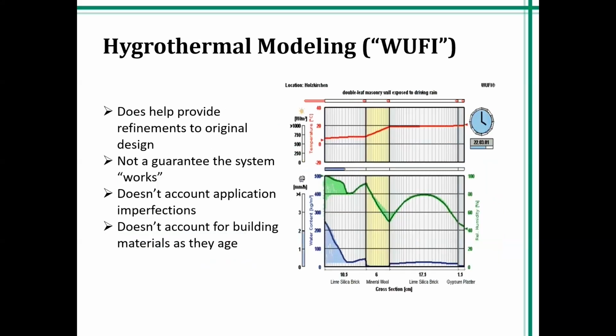These are some of the comments from, again, my CSI colleague, who I'm surprised still talks to me because I pepper him with endless questions about hydrothermal modeling. It does help provide refinements to the original design. However, it is not a guarantee that the system, quote unquote, works. It does not account for application imperfections, and really importantly, does not account for building materials as they age.